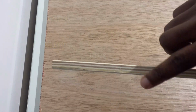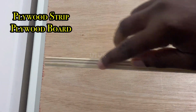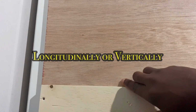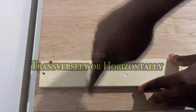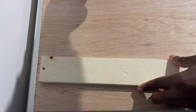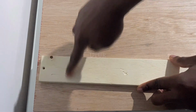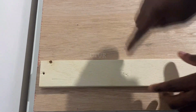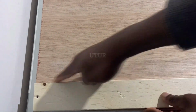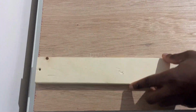Here we've got a plywood strip that's been stripped off the plywood board, and you can tell by the layers on the side. And so although you need a ripping blade to cut wood vertically along the grain of the wood, and a cross-cutting blade to cut across the grain of the wood horizontally, you might be tempted to think that getting a cross-cut blade to cut across the grain of both the strip and the plywood would be the best blade to get. And you might also be tempted to think that getting a ripping blade to cut along the grain of the wood vertically would be the best blade to get, when cutting the plywood strip and the plywood board.